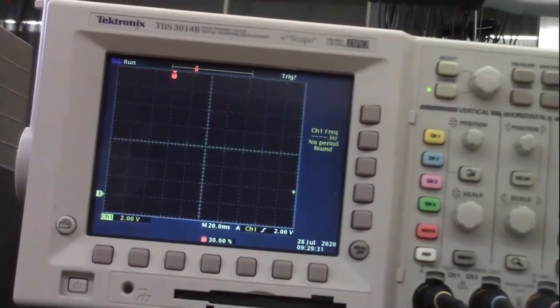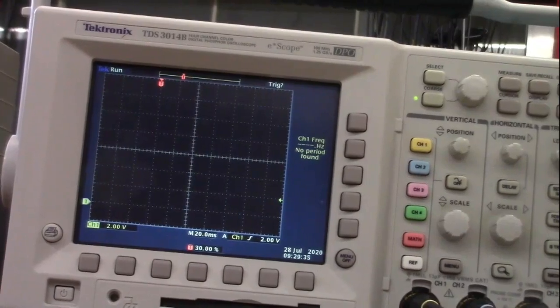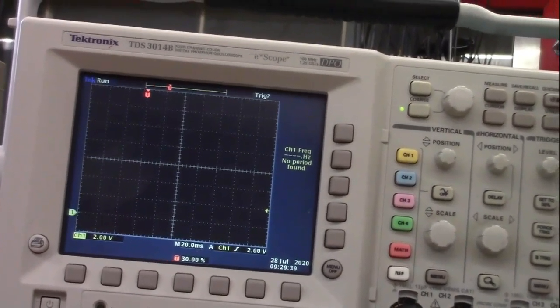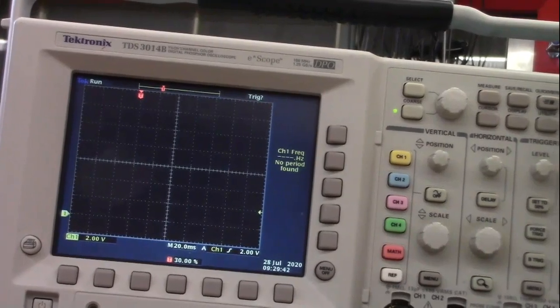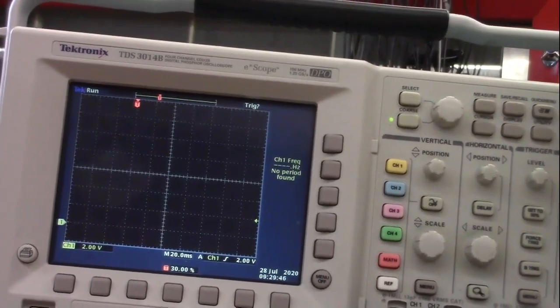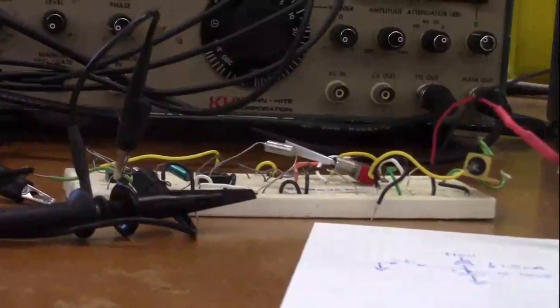We have our oscilloscope. Our oscilloscope is set to trigger just once because the phenomenon we're going to look at, which is the charging of a capacitor, starts when we release a button and then ends when the capacitor is fully charged, and it's only going to happen each time we press the button. So we're using the single sweep, single trigger mode of the oscilloscope. And finally, we have our test setup.